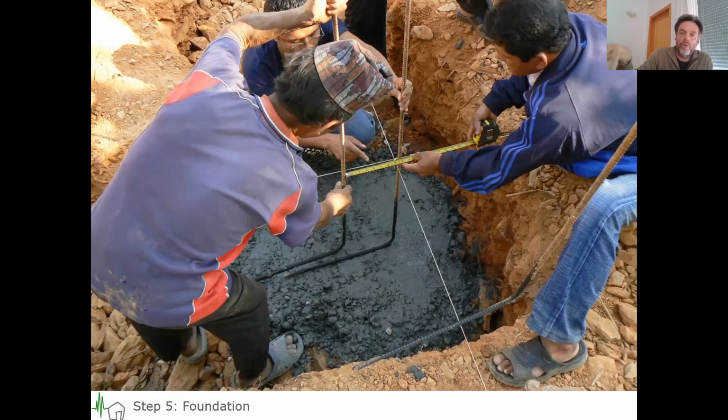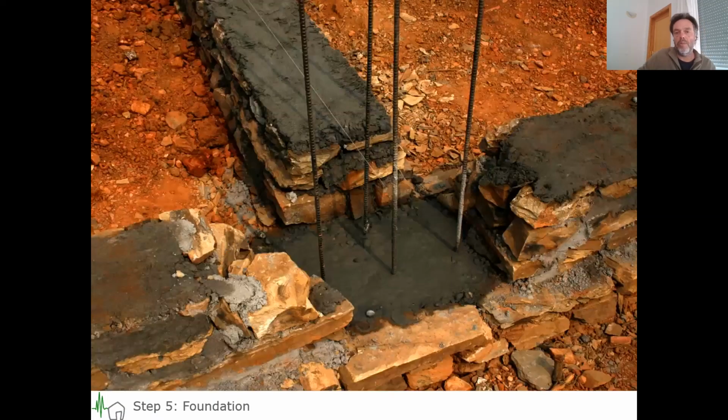In the first school, we went all the way down to the foundation. And then we found out that it was very difficult to connect. So we learned here already that, first of all, we doubt that it is necessary. We probably can start on top of the tie beam, that's what we did in the next school. But we saw that we started interrupting the foundation. Now, it is below ground, so I think we can get away with this sort of hybrid solution. But we learned here that it's difficult to place stones around steel bars.